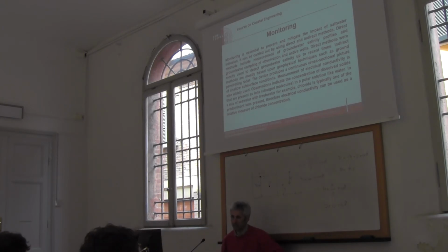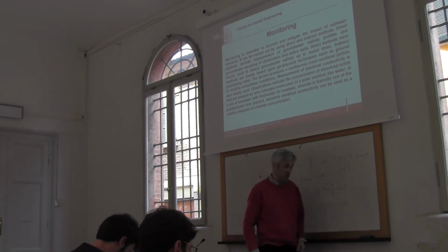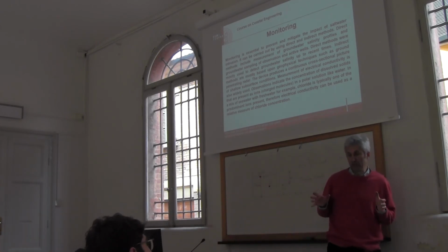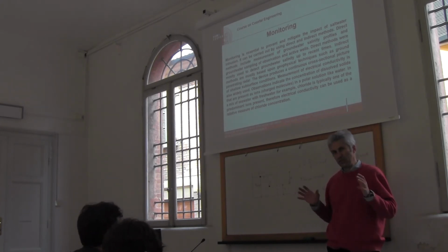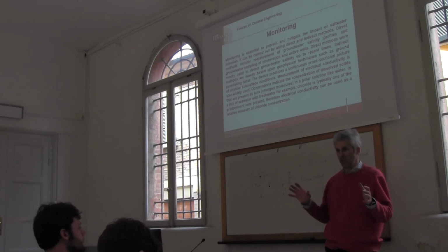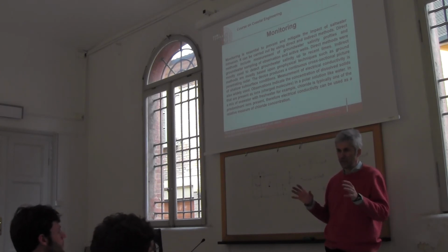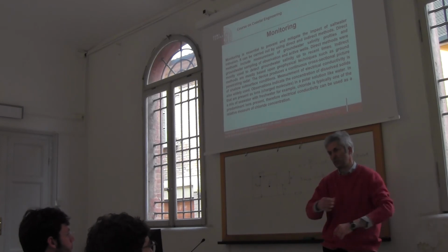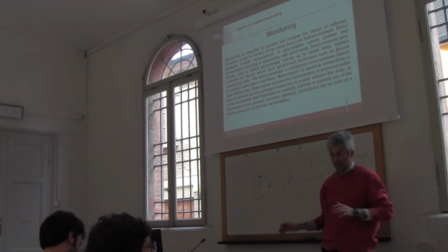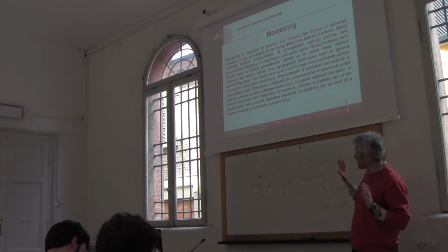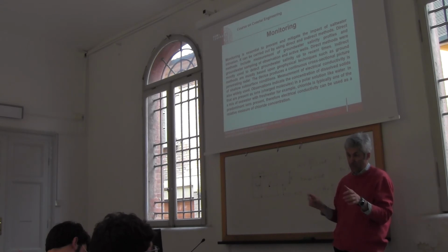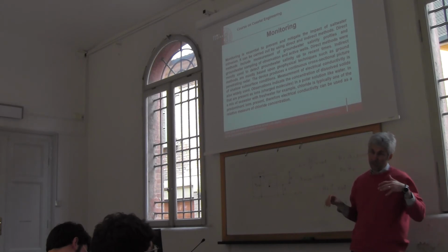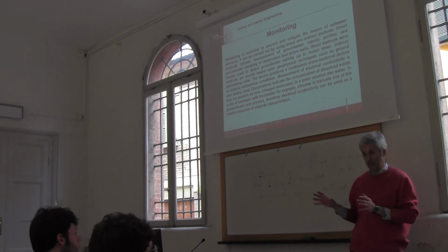Monitoring is essential because to understand the dynamics of aquifers, which means groundwater, is not so easy, because it's difficult to observe these water bodies. While a river can be easily observed, a groundwater body is difficult to observe, and therefore what we need is to make an effort to observe them. And in order to observe a groundwater body, the most applied solution is to use wells.